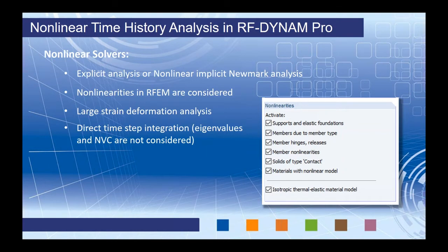With either one of these solvers, nonlinearities within RFEM are now considered. So the question might be, what exactly are these nonlinearities that we can consider from RFEM? Here is a nice screenshot showing you the global settings within RFEM where you can activate or deactivate some of those nonlinearities. So as I already mentioned, the member type, tension only, compression only, cables, but we also have